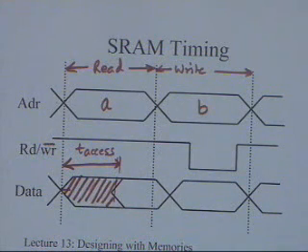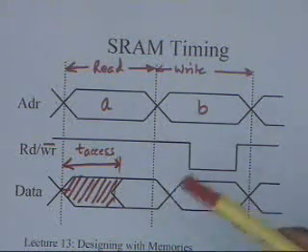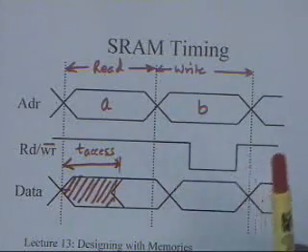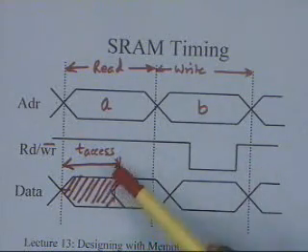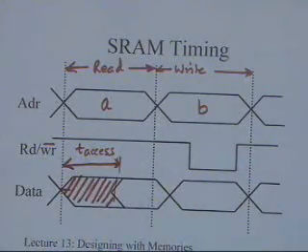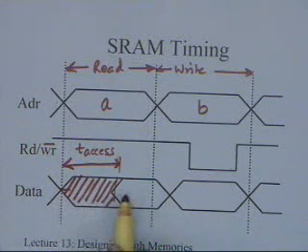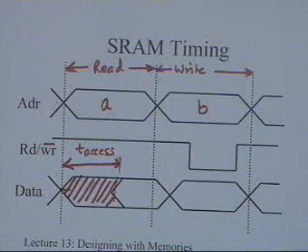So if you say that your access time for the RAM is 60 nanoseconds, what it means is, from the time you supply the address, it takes that time to select the proper location which needs to be read. After all, if it is a 16 kilobyte RAM, you have to do a lot of decoding to get to the actual cell on which the data is stored, and that is the time that is related to the T access time. And during this time, your output is not really defined.